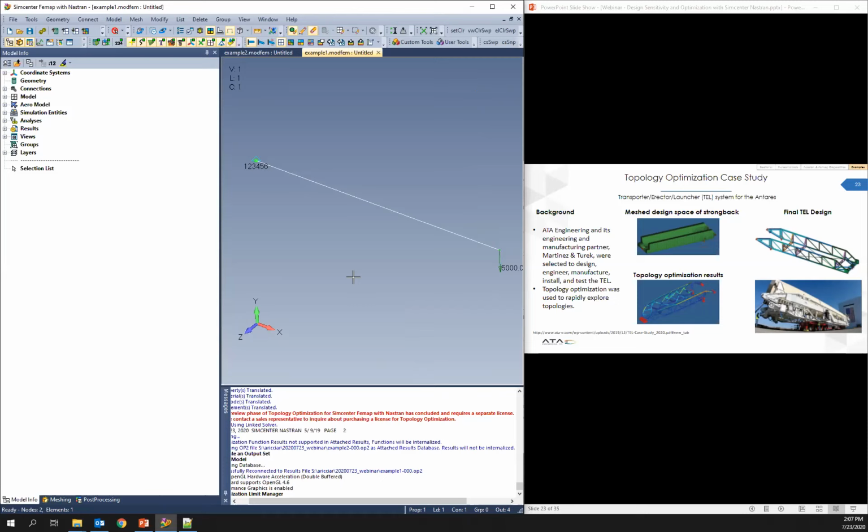the design variables need to be continuous. And so things like individual ply thickness and ply orientation, you can use the optimizer directly as shown in these examples to optimize those quantities.